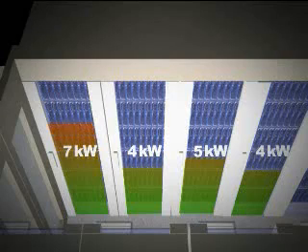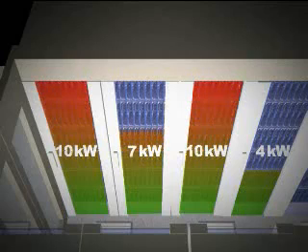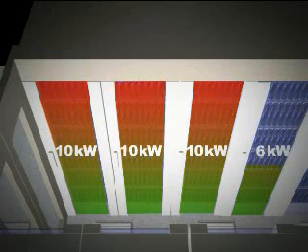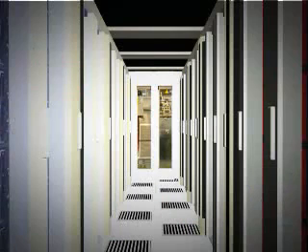As a byproduct of encapsulating the cold aisle, you can also increase your power consumption per rack, typically from 5 kilowatts to approximately 10 kilowatts per enclosure. This now enables Rittal to provide a low-cost, lower-footprint, medium-density data center with a very simple mechanical add-on.